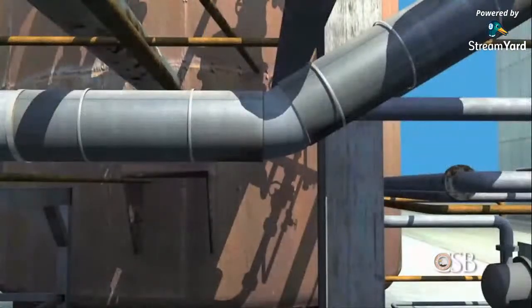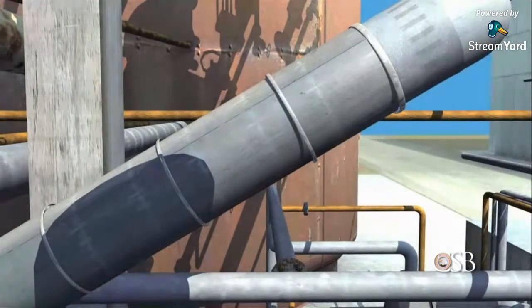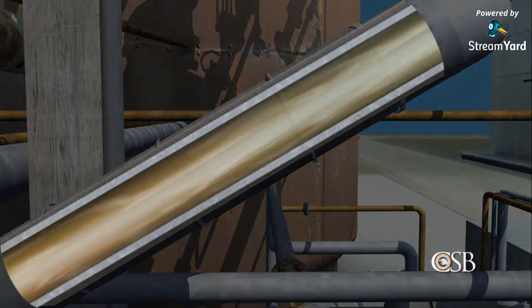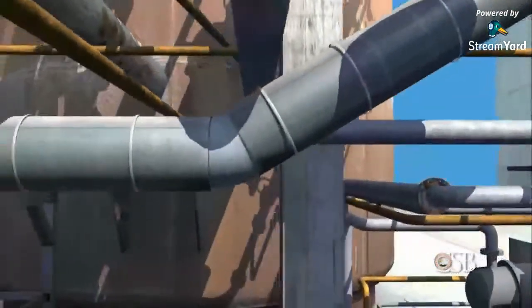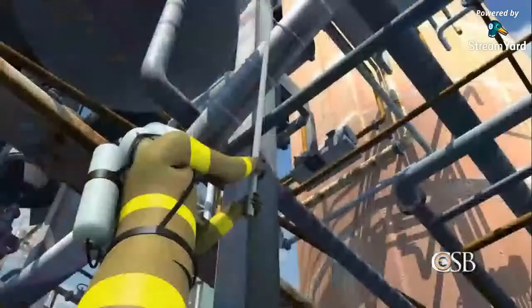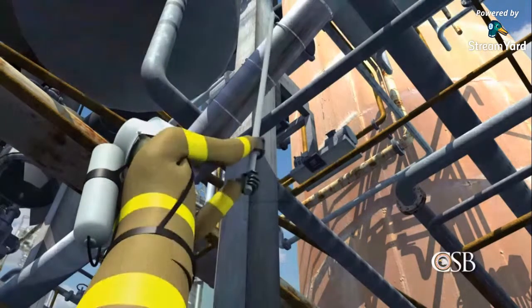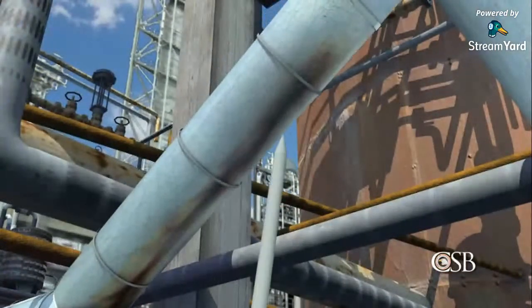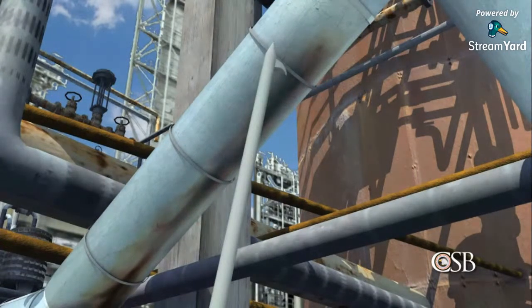The group discussed a recommendation from an operator to shut down the unit, but they decided to first try to pinpoint the leak by removing insulation from the pipe while the crude unit was still running. They hoped they could stop the leak with a temporary metal fitting known as a clamp. A Chevron firefighter tried using a pike pole to hook and pull away the insulation, but this poking action was deemed too dangerous because it was moving the pipe. The CSB later found that the tip of the pike likely caused a small puncture in the already thinned pipe.